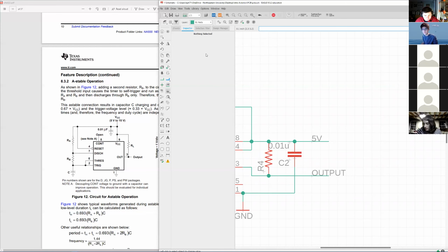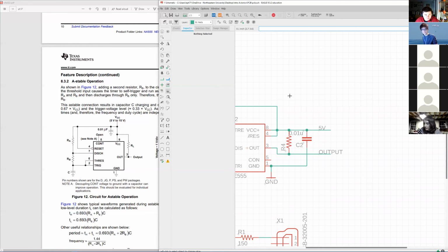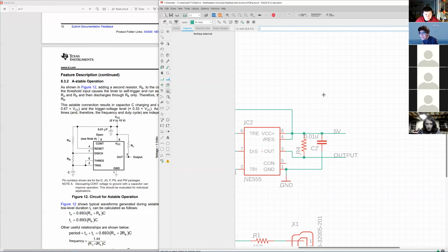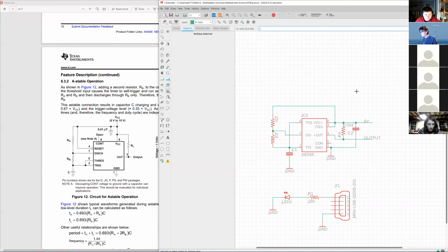We don't need the F, because it's a capacitor, it's obvious. There are lots of tricks to shorten things. I had to read schematics from an engineer that was like 60 something. He just writes 1. If a capacitor says 1 on it, it's a 1 microfarad capacitor, because you'd never use a 1 farad capacitor.